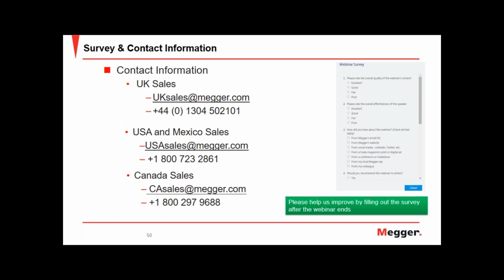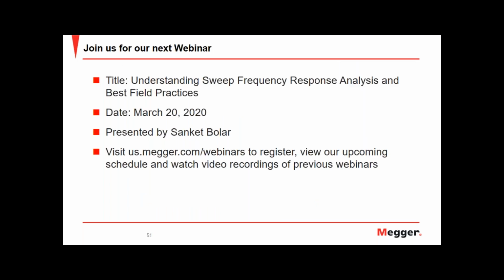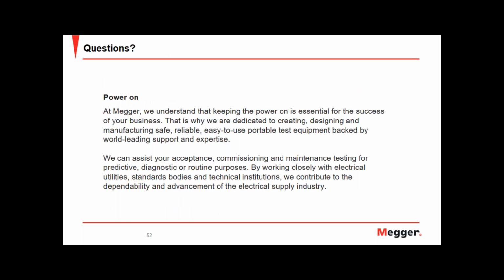So the most common method is to keep some heaters in the equipment. So very likely the panels or the motors, if it's an important motor or an important dry type transformer or any place that could hold moisture, they will have heaters that as soon as the equipment is de-energized, they automatically will be turned on and will keep the environment or the surroundings dry and warm.